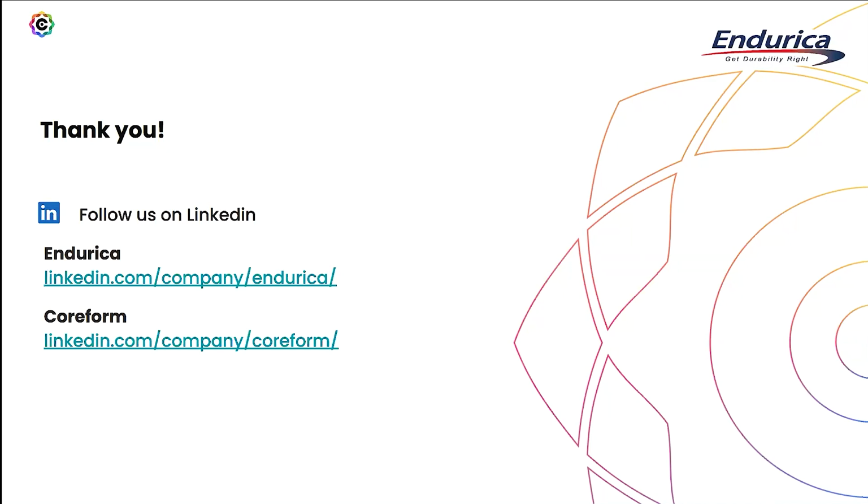But things smaller than that, we tend to treat them as, the way Endurica works is these crack precursors. We assume that they're a small penny-shaped crack. And Mark mentioned this idea of critical plane analysis. What critical plane analysis means is that we take that penny-shaped crack and we calculate what the fatigue life would be, assuming that it takes different orientations.